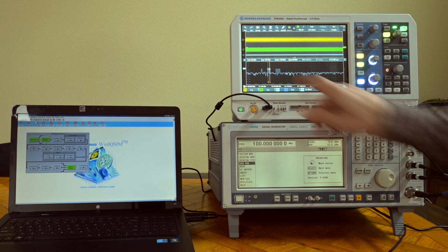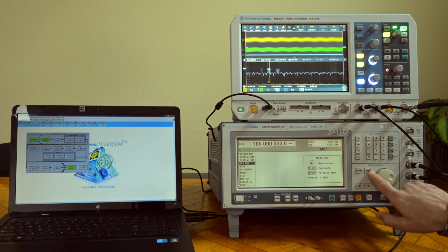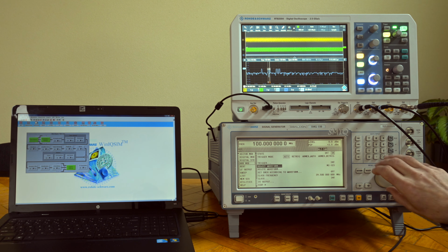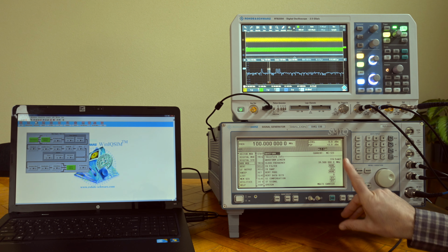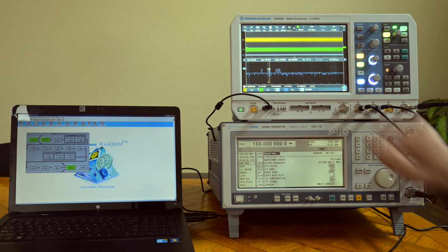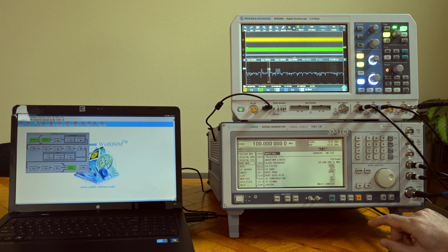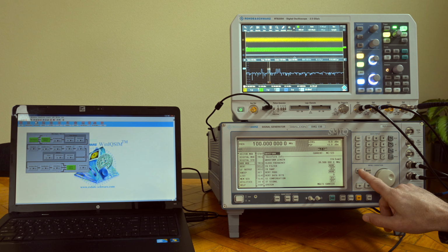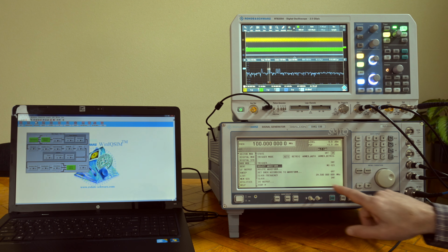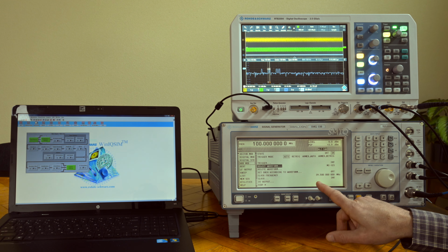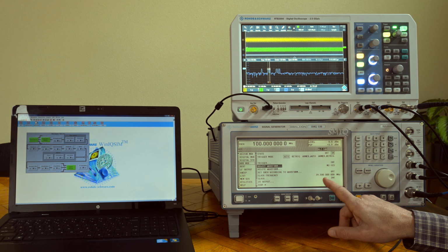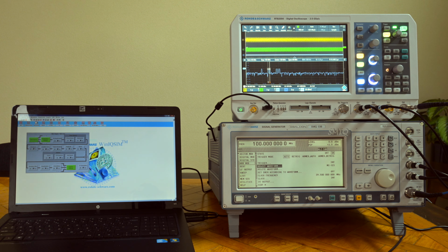And yeah, wonderful. We already see the signal, but let's first go to the modulator. And what we see is select waveform. So this is the waveform we just created. It's 360 samples, and amazingly enough, we get the right signal with 300-something samples or so. We've got here some of the data that we can still change about it. And in the overall menu, we can do the triggering stuff. We can do clock frequency changes, and of course we can do the modulation and the level as with any device.